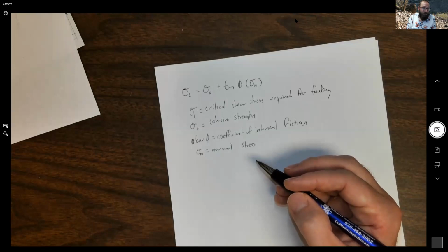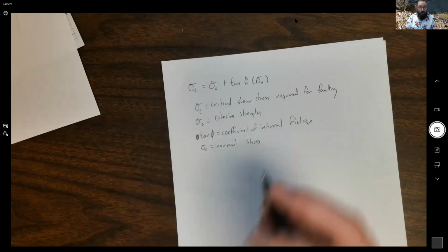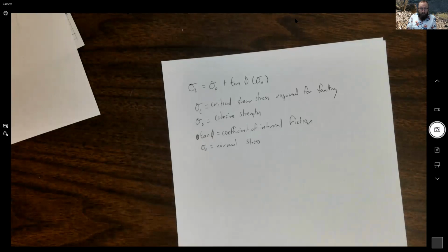To emphasize also, it's on homogeneous rocks, so fracture-free and fault-free rock, and free of anisotropy, which we'll talk about later in this video, under which we have constant confining pressure applied. So in other words, sigma 3 remains the same, and we amp up the maximum principal stress, sigma 1, until the rock fails.